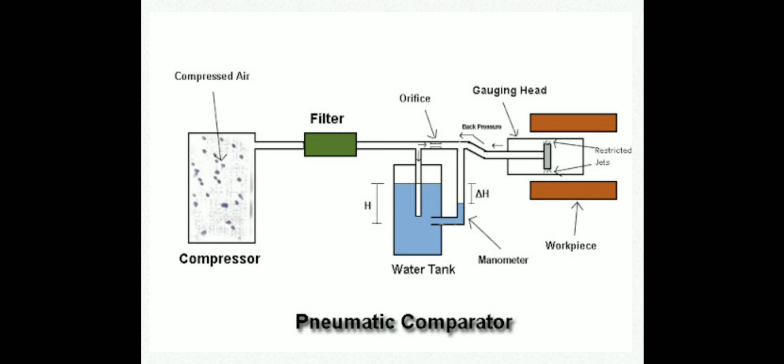Similarly, for the back pressure type pneumatic comparator, the basic principle and theory of pneumatic gauging in back pressure gauges is described. Air from the constant pressure source flows to the atmosphere through two orifice pipes. Here the pressure upstream of the first orifice and the pressure between the two orifices are both measured with reference to atmospheric pressure as datum.